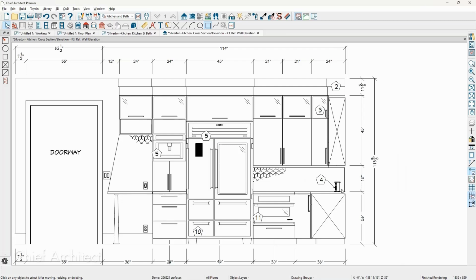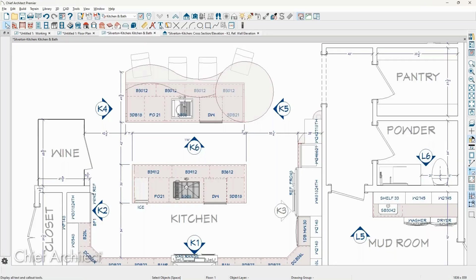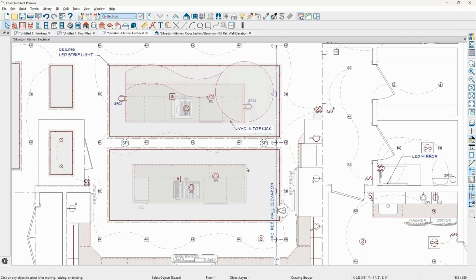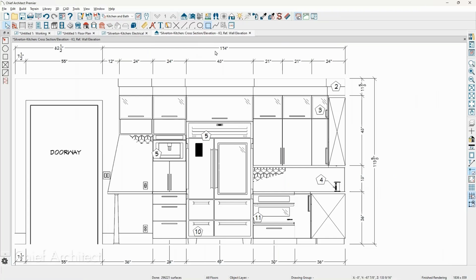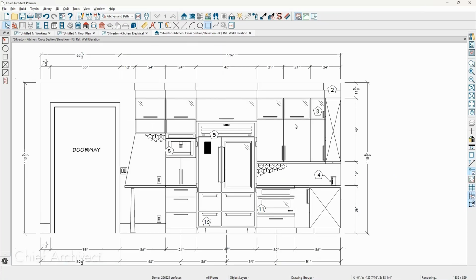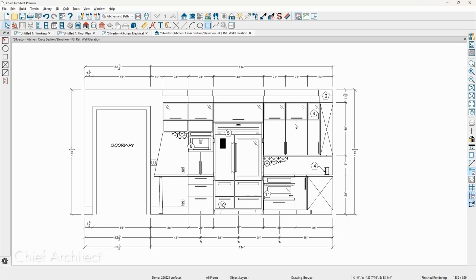The only other thing I could recommend is doing an electrical elevation view. And that's what I'm doing at the moment. Yeah, and that way you don't have to draw a separate CAD over there. You've done your electrical plan, right? And rather than having two of these, we switch over, because a lot of times this electrical isn't enough in a floor plan view because it doesn't give you where the elevation is for this refrigerator or wherever else you've got. And so if you built a view for just electrical and an elevation, and then you dimension those aspects and do a note call out for it, that would be the other way I'd recommend.